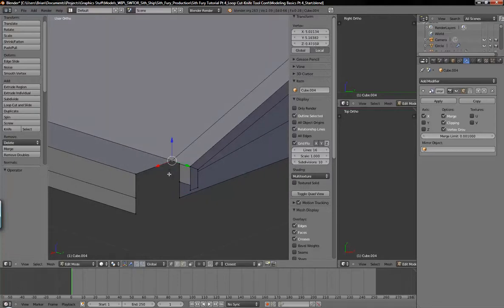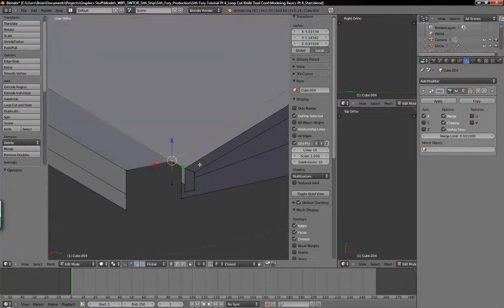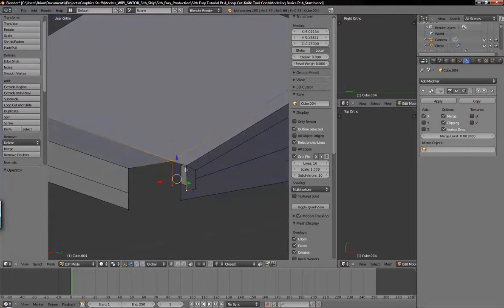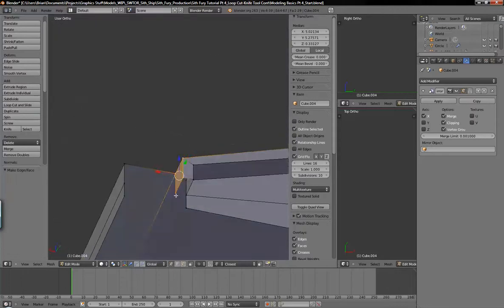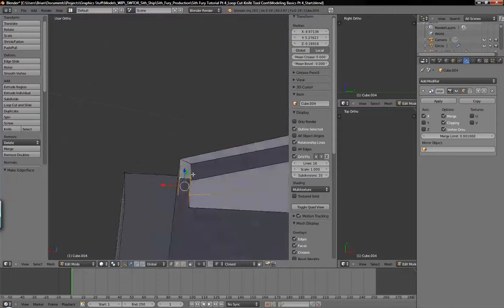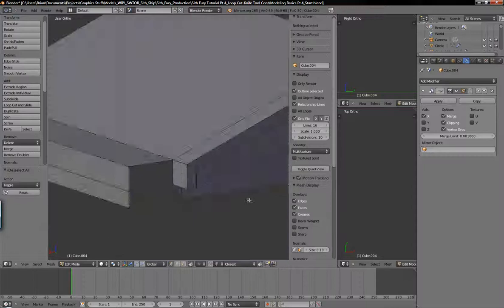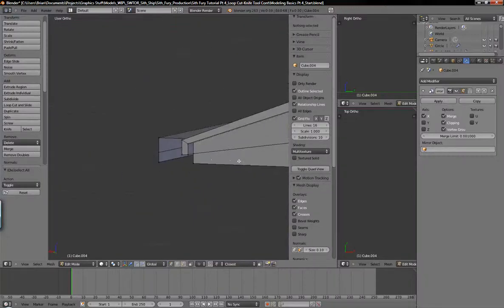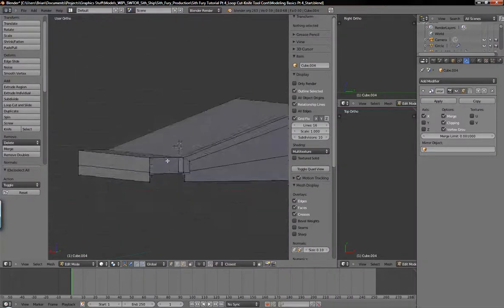So select that vertex again. I'm going to just do this, just highlight that. Control C, just left click out of there. Grab this vertex, go back in here and Control V, and then left click. So now we can just close this edge off here. And we'll select these points and hit F to create a face, and that will do it for that.